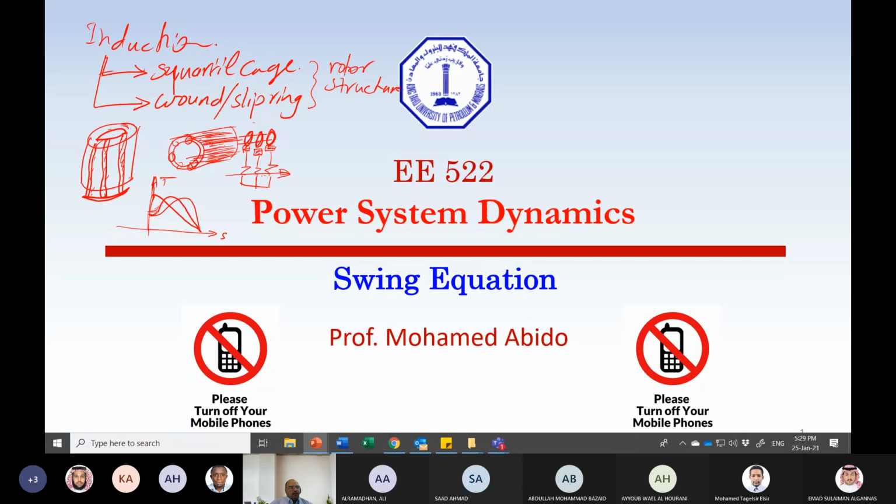You know, if the load torque is above the motor torque, in this case the motor will not start. If this is the load torque, that's okay: the starting torque is higher than the load torque, so it will go. But if the load torque is here, the motor will not be able to start the motion. So you can play with this resistor in order to have a very high starting torque, so you can go. So this is the classification of induction.